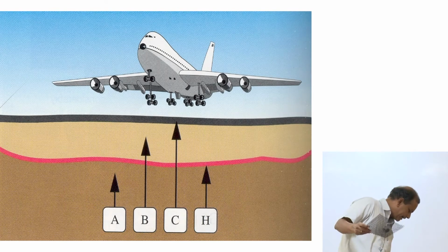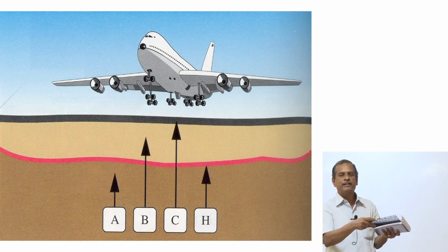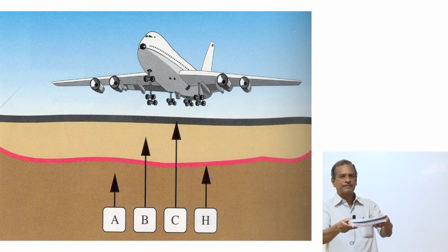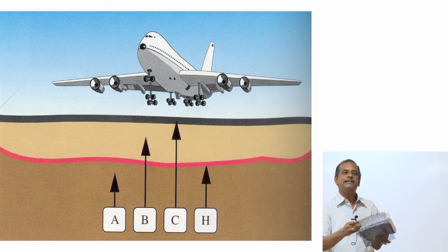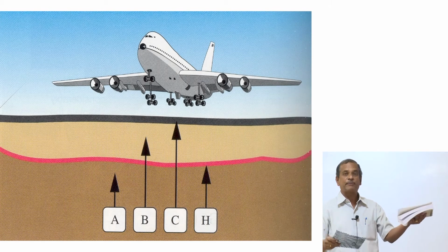The next question is, in a given pavement layer system, where should I keep this? At one-third from the bottom, mid depth, where should I keep it? And what will be the improved strength of this layer system with the geogrid? So this again has to be done only by a civil engineer. Everything costs money. If you introduce a new material, that's improved performance at what cost?